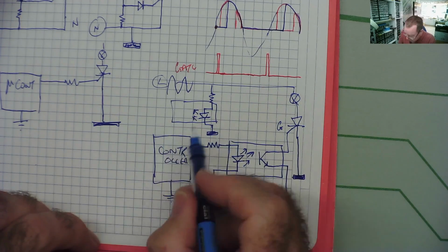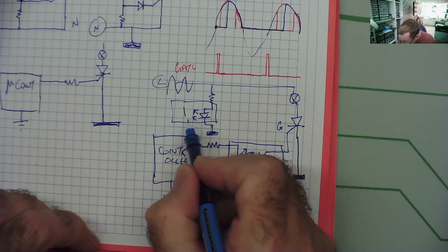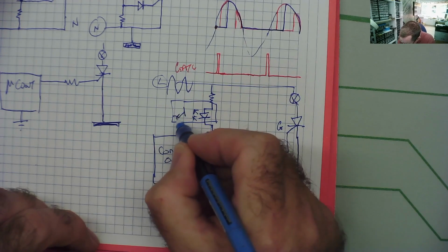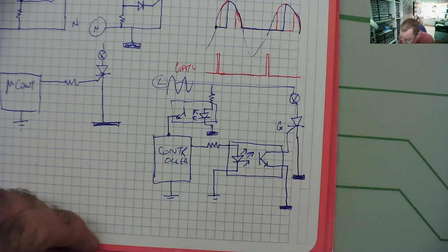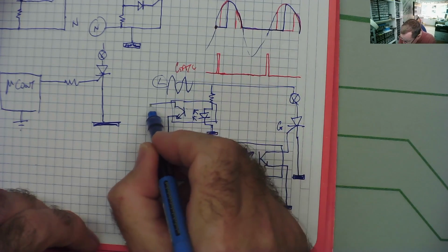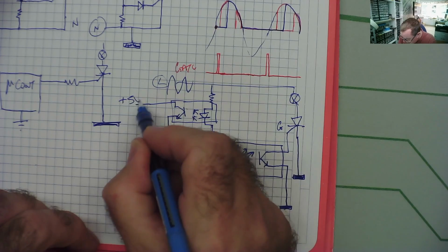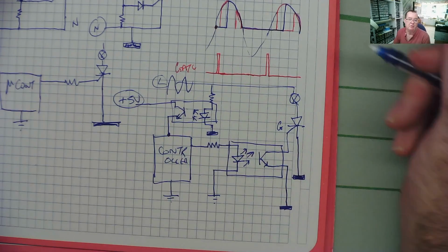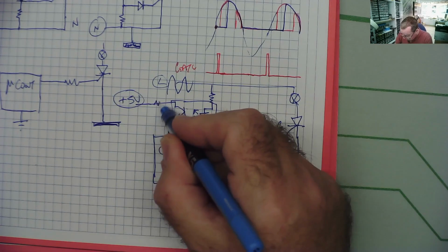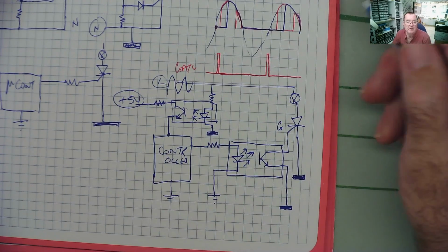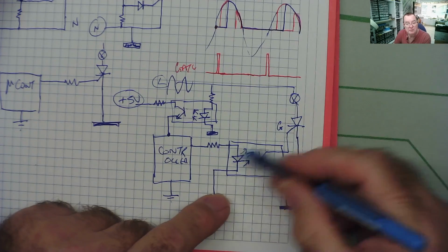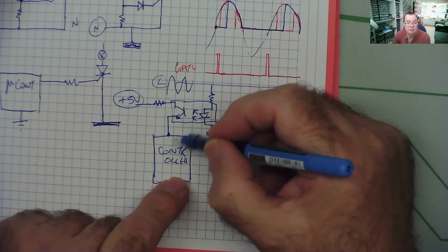And inside the opto-isolator is the phototransistor, another one. The emitter can send the signal to our controller, and the collector can now connect to our low voltage supply, 5 volts or whatever the logic's running on. So we'll probably have a resistor in here, but you can do that, and you can see that this one is driving the thyristor, and this one is monitoring the zero crossing.